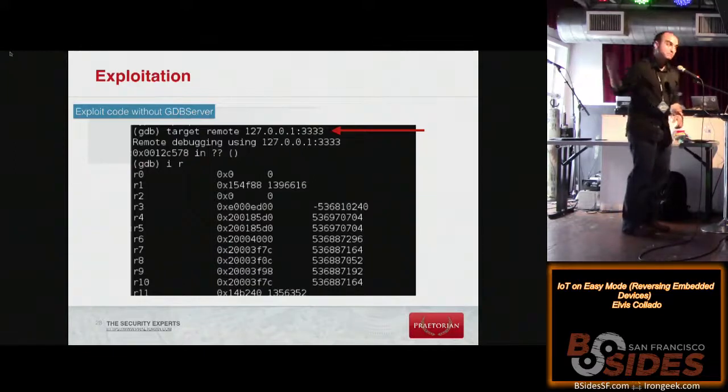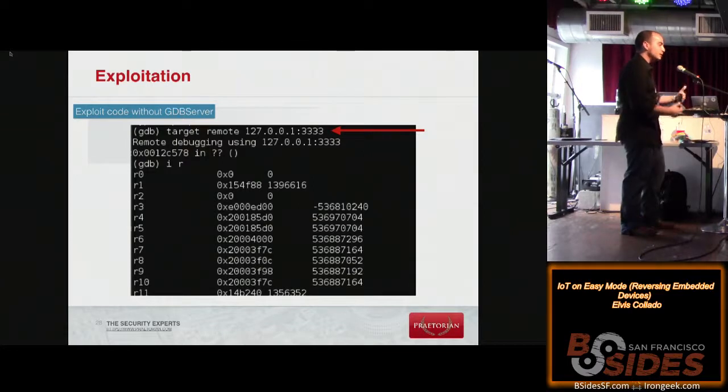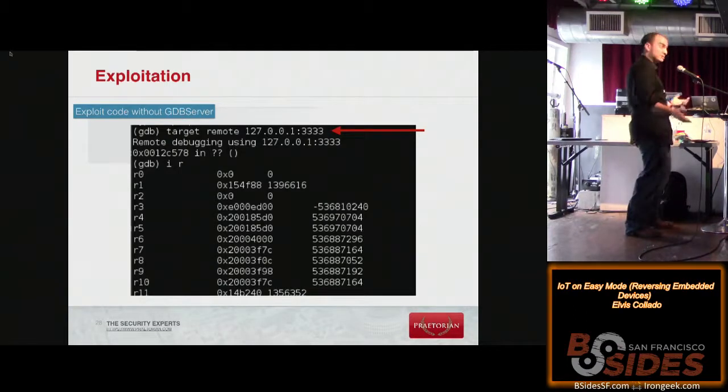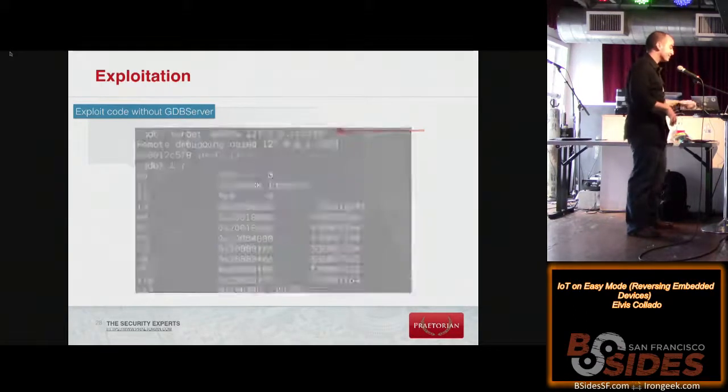And you can start dumping memory. Look at the datasheet for that Cortex processor and see what memory areas are for what purpose. So not everything. You're not going to get a device that's going to use null to all Fs for 32-bit space. You're not going to have 4 gigs. So you're going to find the specific areas and you can dump all that stuff and you might get some useful information. Like for example, on one thing I saw the AES keys right there in plain text and ASCII in memory, and I was able to pull that down for some sort of protocol. I can't go into that right now.